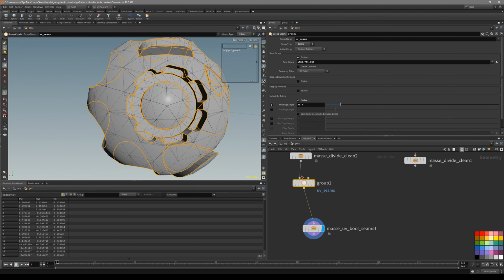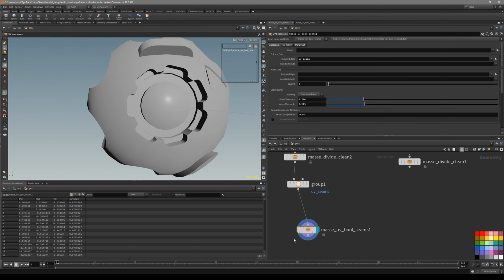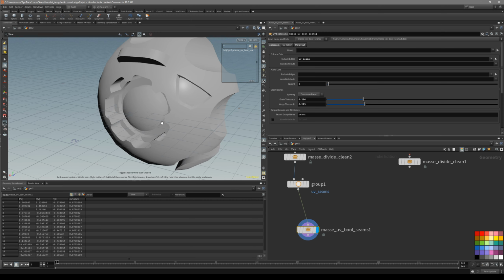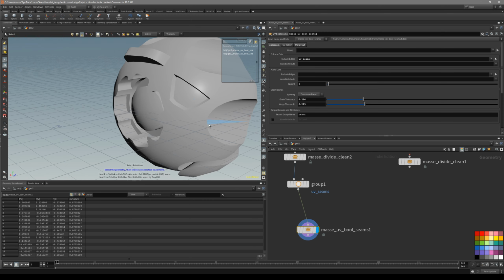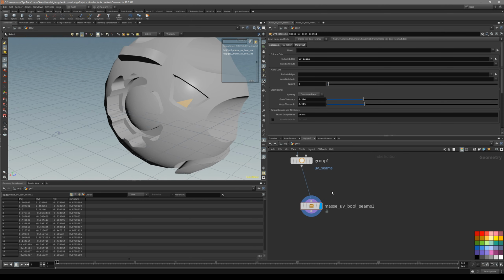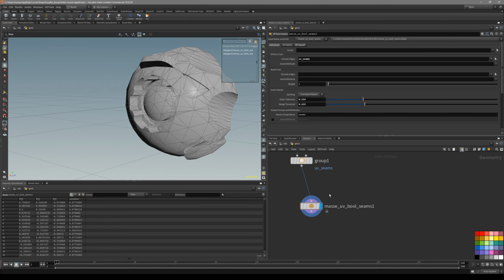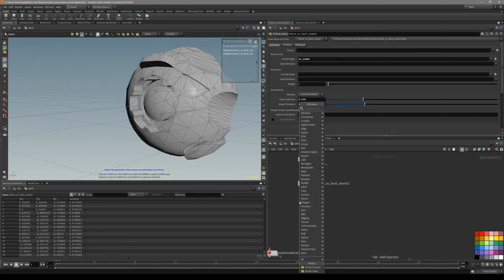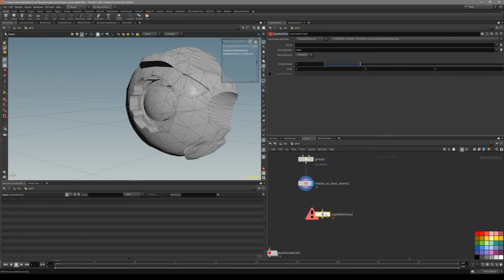So now we have triangulated, UV'd, now we actually can bake it out. So for that we have to actually explode the mesh beforehand. So that happens pretty easily. There's actually a node for it. Let's put down explode node. This is called explode U, and you see it's basically going to ask for the piece attribute.